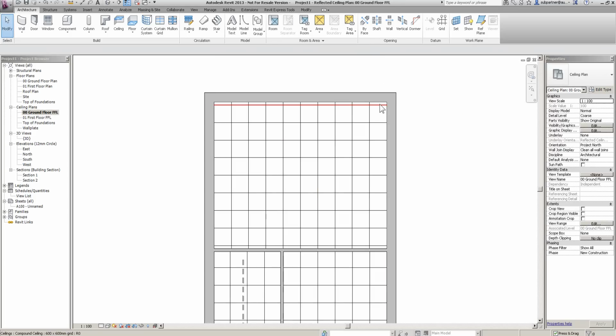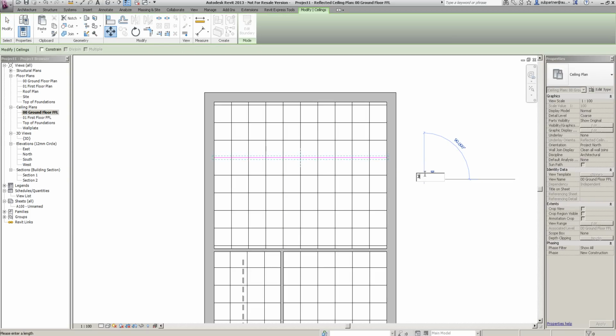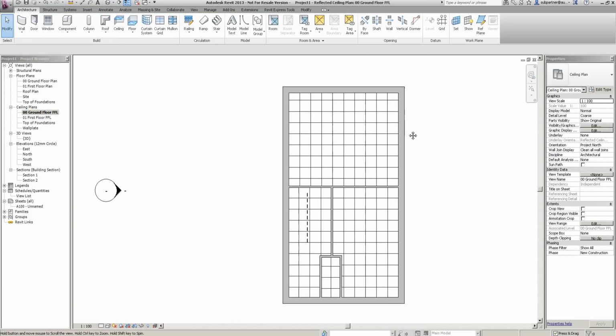For example, in reality, I'm going to move this grid. Now what I'm going to do, I always teach people to create things on their BIM model how you're going to do it in the real world. So in the real world, if you've got a silly little cut across there, your entire grid system would move half a tile. So that's exactly what we do. But we don't move half a tile. We pick one of the lines involved in the tile, move from here, go up 300, which is half a tile, done. And the rest of the grid will just basically align to it.